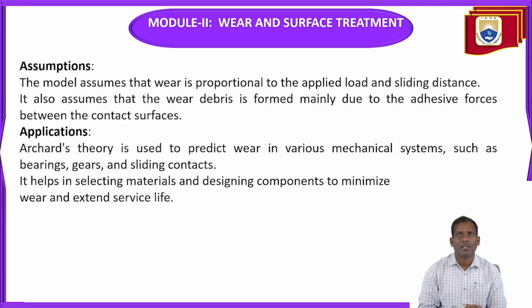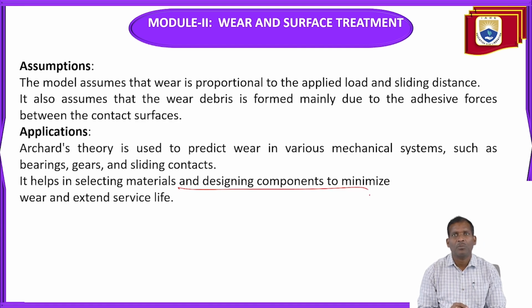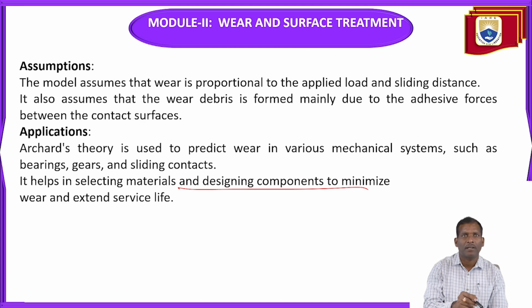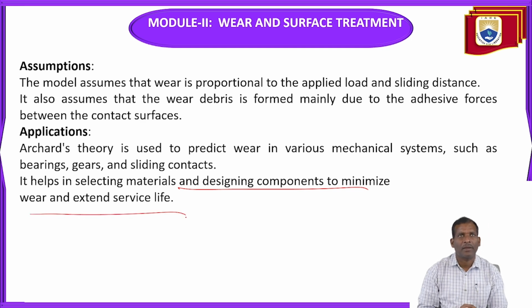Some assumptions are made, that is, the wear debris are formed mainly due to the adhesive forces between the contact surfaces. The application of the theory is to predict wear in various mechanical systems such as bearings, gears and sliding contacts. It helps in selecting materials, designing components to minimize wear and extending service life.